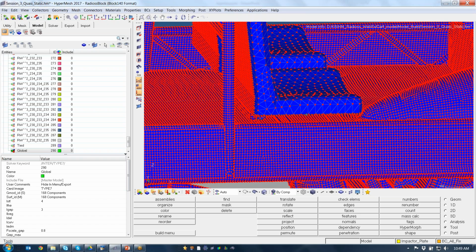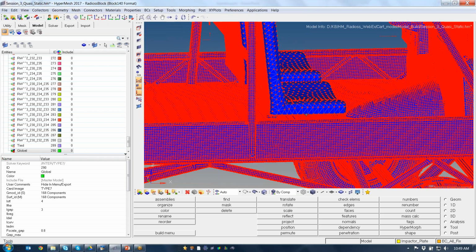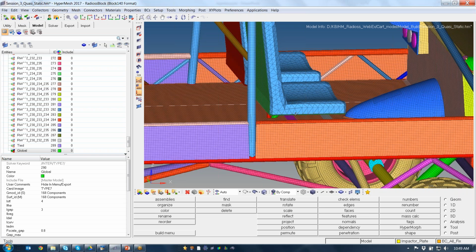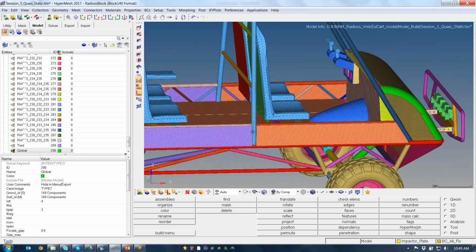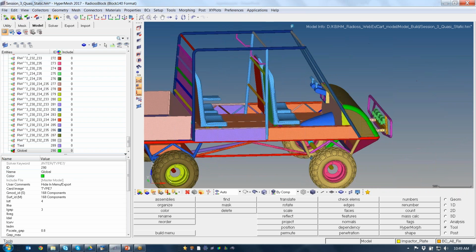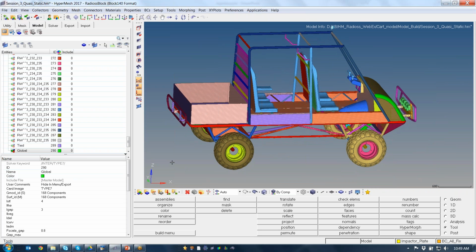But that doesn't matter, you can have both type 2 and type 7 in the same location. And type 2, what we created for this seat also, is a contact, but it is a kinematic contact, and what we are creating now is a penalty based contact, basically sliding contacts. Okay, so we created type 7 successfully, good.